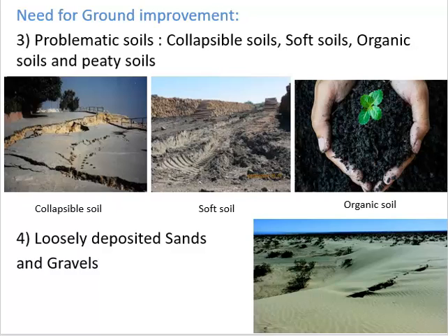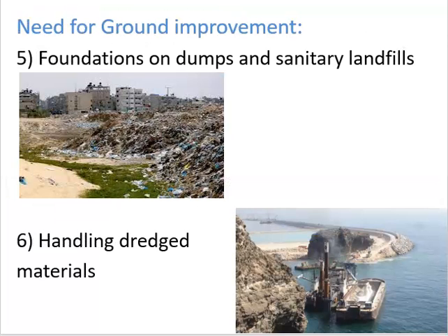Then loosely deposited sands and gravels. The coarse grained soils, if they are loosely deposited, may form sinkholes in rainy season and disrupt the foundations. Next point is foundations on dumps and sanitary landfills.